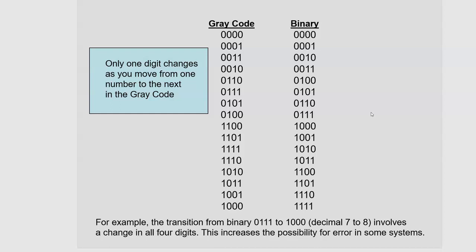If you watch an old school TV set, you might be watching and your mom or your girlfriend or boyfriend, whoever, turns on a mixer or vacuum cleaner and it puts these little lines in the picture. That's noise, and that noise might be coming through the house wiring, but it could also, if you have a motor that's running like a mixer or vacuum cleaner, anytime you have anything that creates an arc, it creates a radio wave that other circuits can pick up, and it can cause noise.